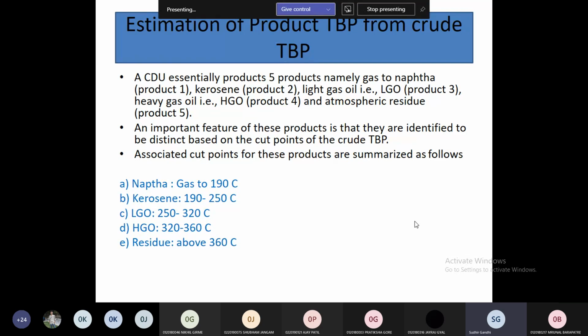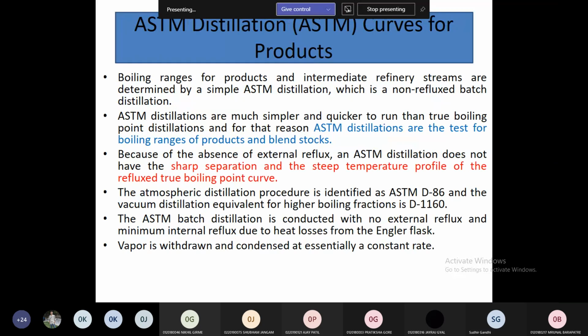So basically we will end up with what we want. We want the lighter fraction to be produced more. Maybe if we want more gasoline to be produced, we will need more treatment, because from the heavier fraction, we will be converting it again to a lighter fraction. So maybe the cracking feed will be more. In that case, we need to operate the cracking unit with higher capacities. So that is the significance of this particular test in a nutshell, right now. Okay. Is it okay?